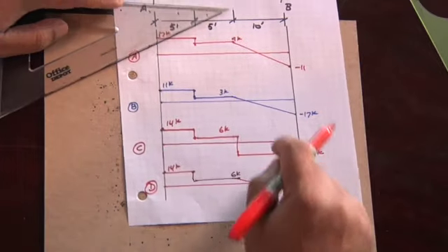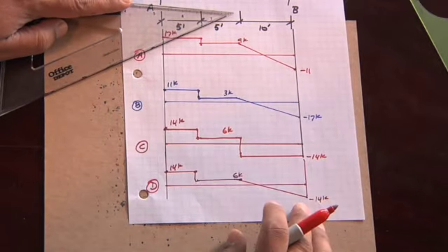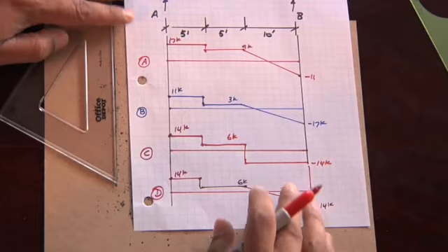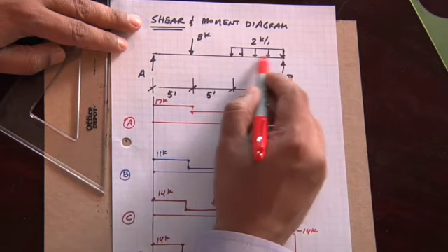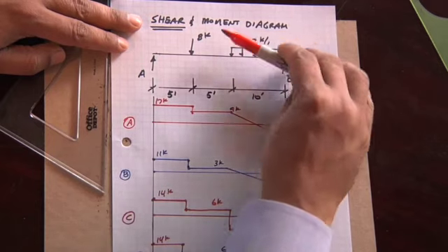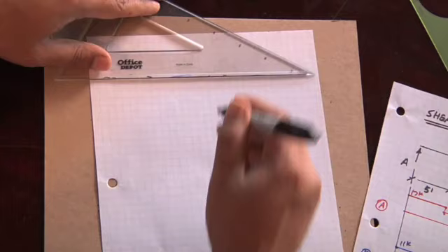So you have 4 options, and we have to decide which one is the correct option. Right away, we can pick one of these as being completely incorrect. Let's do that first, because we're all about eliminating the wrong choices first. Immediately when you look at these options, there's one that doesn't make any sense. Because you have this uniform load, remember that the uniform load causes a slant shear diagram. That comes back from one of the earlier modules. Let's just quickly refresh our understanding so that you're clear on that.